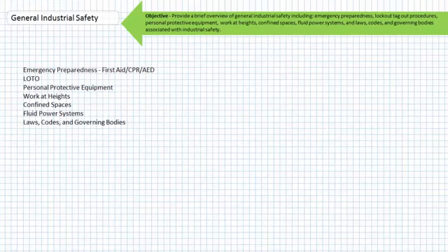Realize there are systems still running that were built way before lockout and tagout procedures became law. These systems cannot be locked out and must instead be placed in a state of zero energy and then tagged out before being serviced. At no point should a tagged out system be operated until all workers owning the applied tags remove them. The success of the tagout system is dependent upon a trained and disciplined workforce.